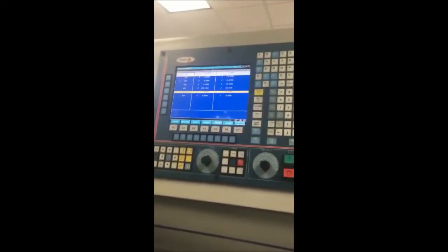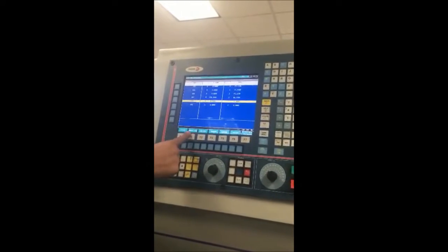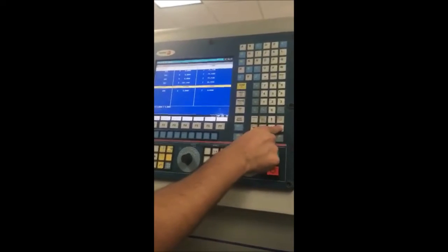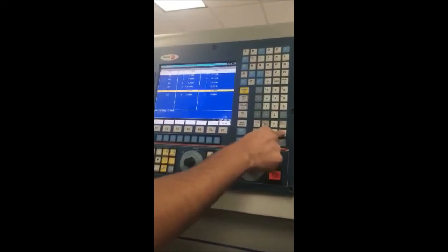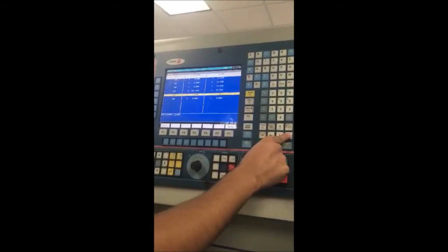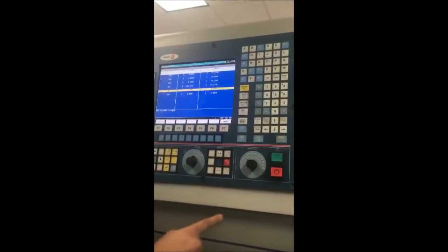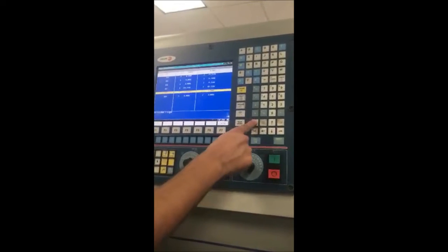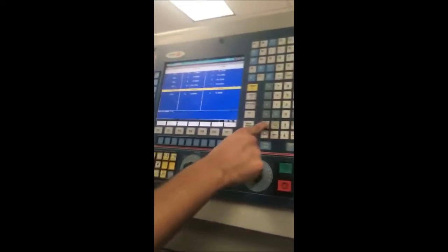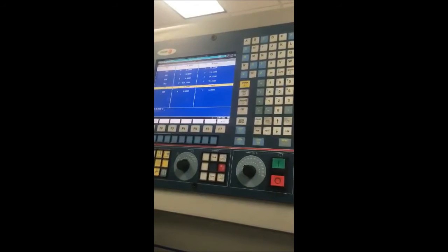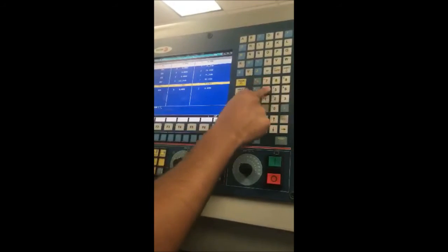You go to Tablas, Orígenes. You select one of the options. You click on Modificar and change the Z value to the length of the part. Then you click Enter. And now your part 0 is completely saved in the computer. Now you have declared your part 0.